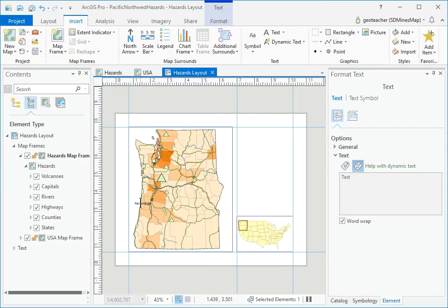In the map, place the mouse on the text to show an insertion bar used to edit the text. Place the mouse near the text to show a black arrow used to select the text box. Select the text box. Click and drag one of the square handles to resize the text. Find the Rotate symbol under the middle bottom of the text. Click and drag to rotate the text to vertical. Click and drag on top of the text box to move it.